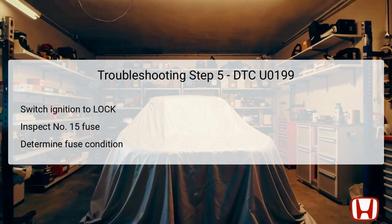At this step, the ignition switch should be turned back to the lock position in preparation for inspecting the number 15 10A fuse located in the underhood fuse/relay box. This fuse plays a critical role in protecting the circuit for the power window functionalities, and checking its condition is imperative for diagnosing communication errors.